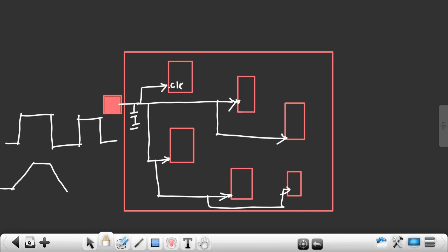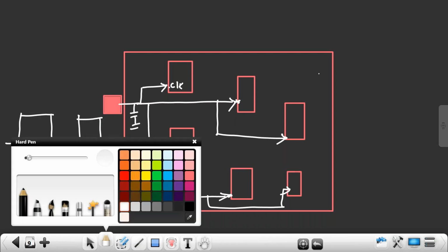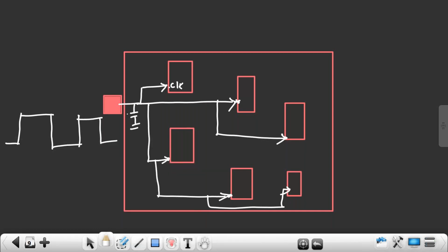It becomes very difficult when we have more load on this clock port. More load means this clock port is connected to many flip-flops. See, I am the faculty, I can handle 30 students, or at most 40 students. If I am given 200 students, can I show the same efficiency? Then what should I do? Split the batches, right? Make a tree. I am one person, the HOD has different teachers. For each and every class, you give a particular teacher, right? Like that, you have to make a tree. Like that, all the flip-flops are driven by a single port. So the capacitance load is very high here.